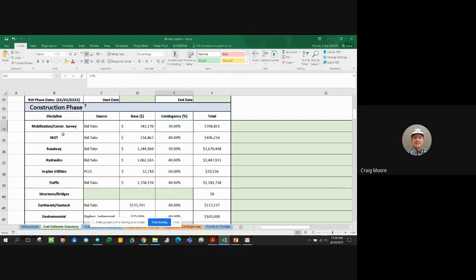as we work through our cost estimate. Traffic, more of your permanent items and your signals. Again, we do show what we're doing there with what will ultimately be our pavement markings and our signal locations. However, there are some considerations as to how that's going to get put in place, so we felt it appropriate to have a 40% contingency there.